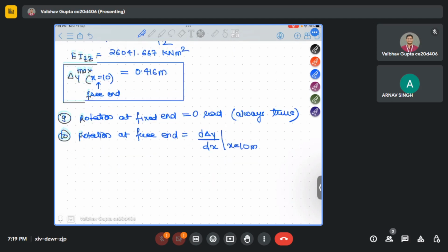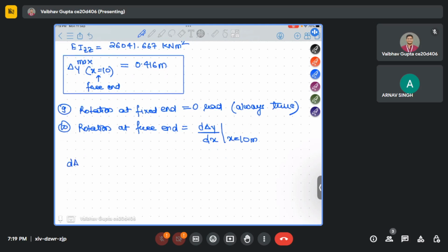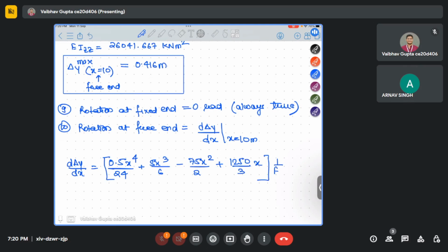So what is d delta y by dx? It's nothing but 0.5x⁴ by 24 plus 5x³ by 6 minus 75x² by 2 plus 1250 by 3 x, all times 1 by EIzz.